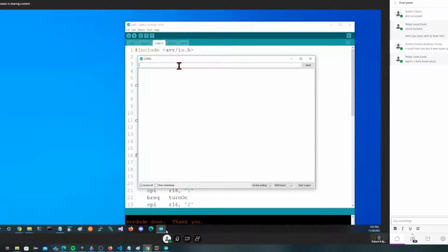Yeah, just because this is who I am, I decided to try something else, and I put in 11, and it reads it as a 1. So this is only reading one character at a time. What if you put in a 1, 2? That's a good question. I know 2, 2 turned it off. 1, 2 blinks on and right back off. Right, it's reading one character at a time because we're processing every time the interrupt receives a new character. Okay, everybody pretty good with that?